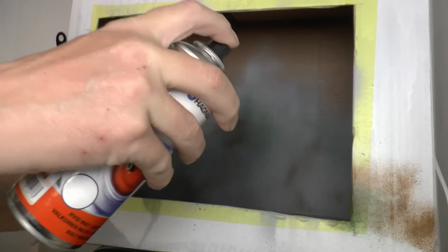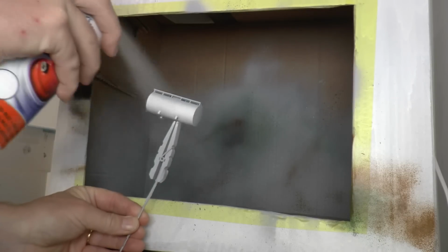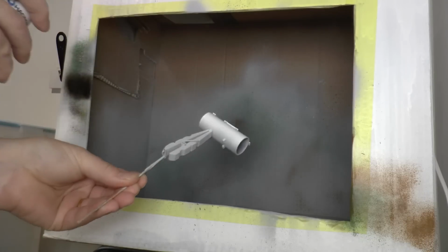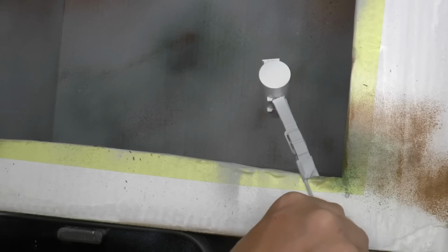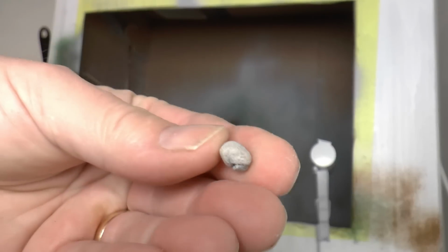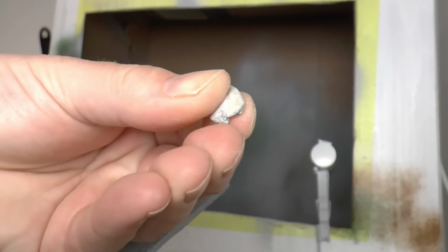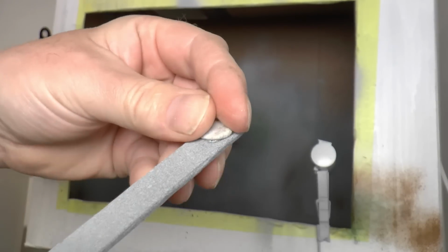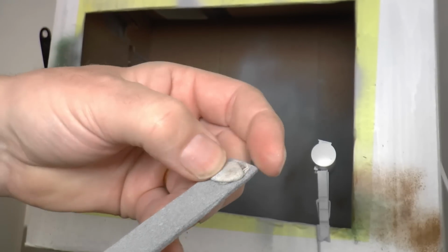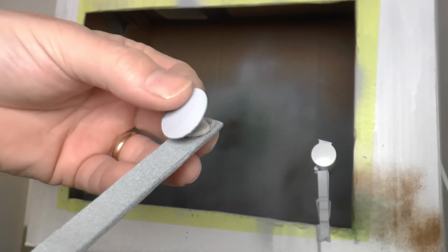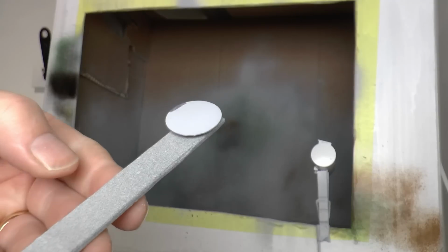I think spray cans work excellent for every item like this, until you get down to really tiny objects. Then the paint tends to be a bit too thick from a spray can, and then you gain a lot by using an airbrush instead. Here's another trick I use when I spray paint. This is a sticky rubber. You use it to stick posters to the wall. I put it here instead on a wooden stick where it holds my 3D printed container lid.